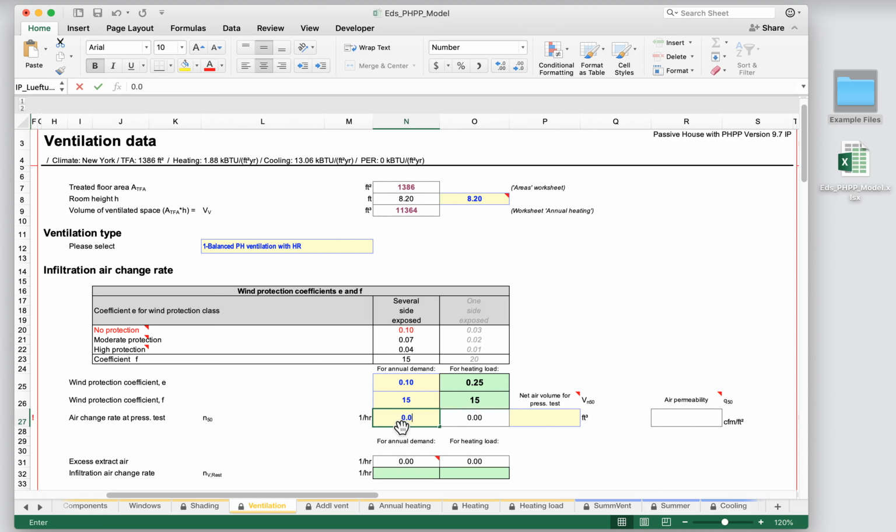You could put 0.000001. And now what you've done is you've said to your build team, guys, we need to build a space shuttle. I would not recommend that. You'll get some pretty good results on your PHPP. Your model would show very impressive heating and cooling energy performance. It would not really have much bearing on reality, because, of course, in reality, you are not going to achieve 0.00000001 ACH at 50.